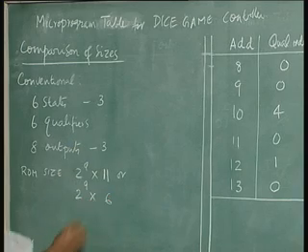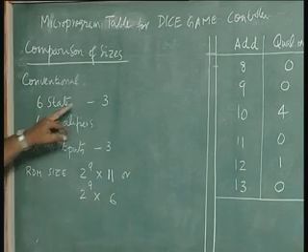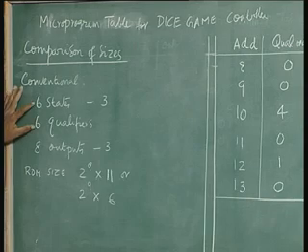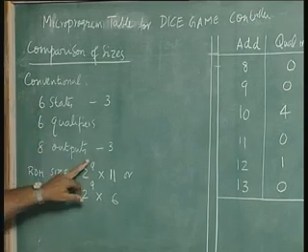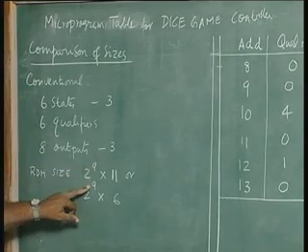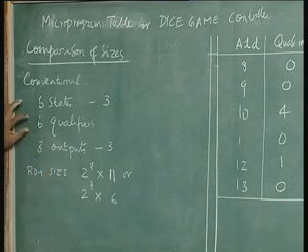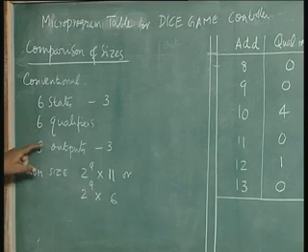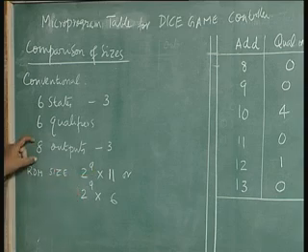That is, each 3 state variables and 6 qualifiers are the input address. So, you have 9 address lines, 2 power 9 is the size. Number of output lines are the state variables and the outputs. State variables are 3, outputs are 8, 11, or if you want to code the outputs into 3 bits, it is 6. Now, microprogrammed approach.